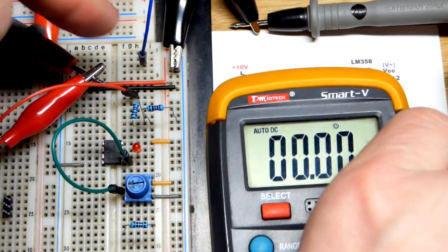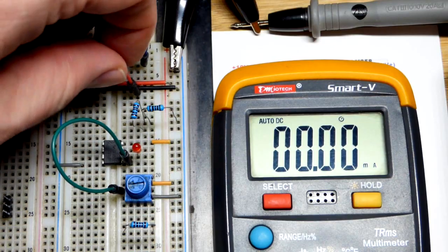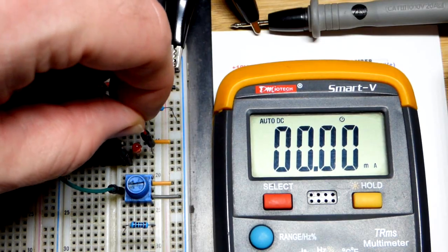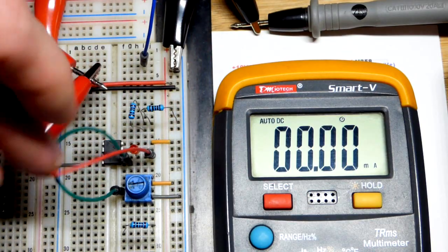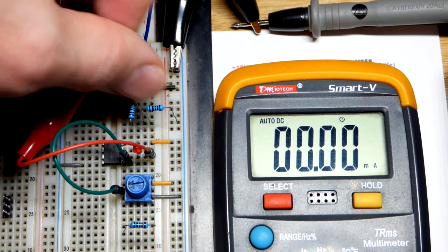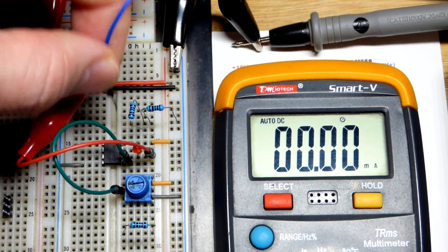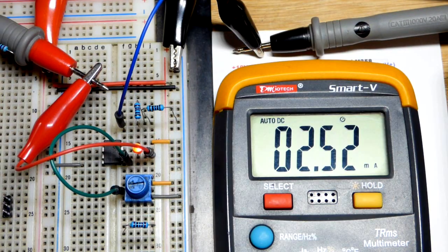So I was careful to make sure that the probes weren't connected to anything electrical right there. And so going to go to where the LED and the inverting input are, and then we're going to get both resistors right there. Current's going to have to go through the two of them before it goes to ground, and there you can see we got about 2.5 milliamps of current instead of 5.